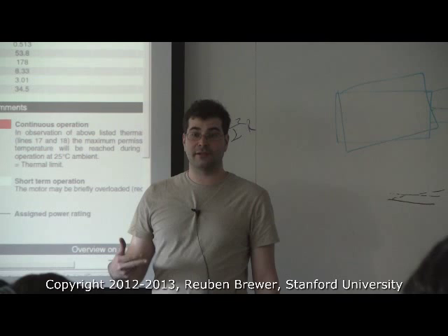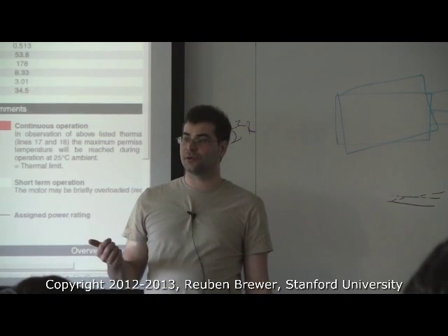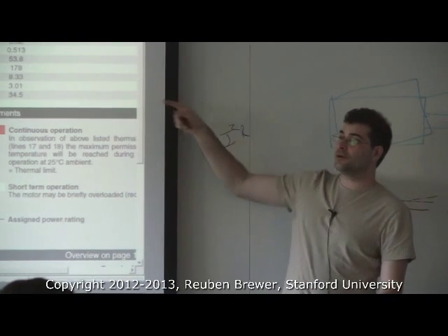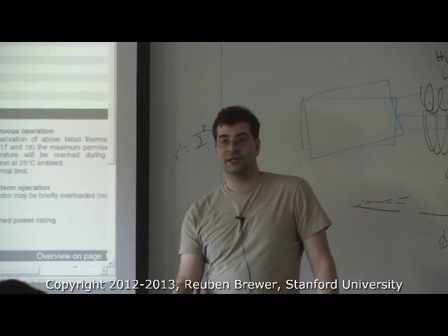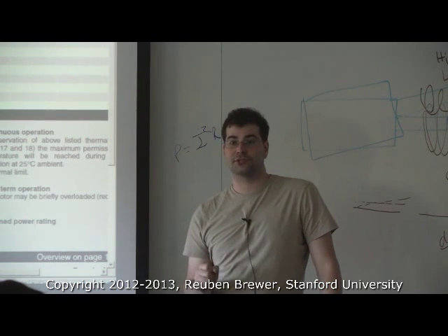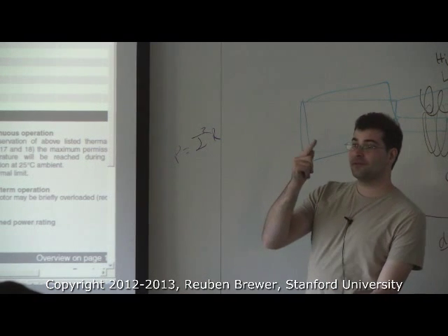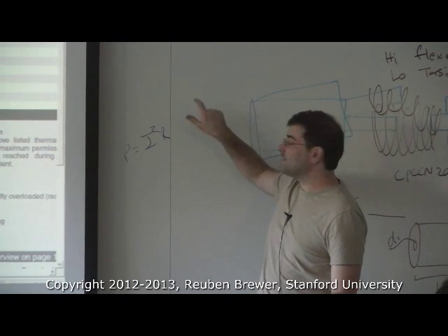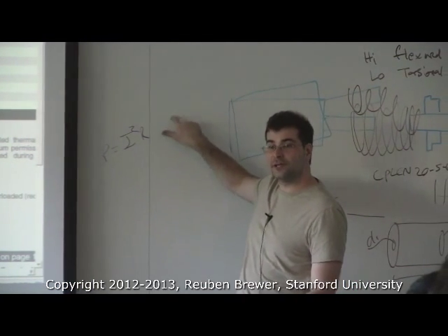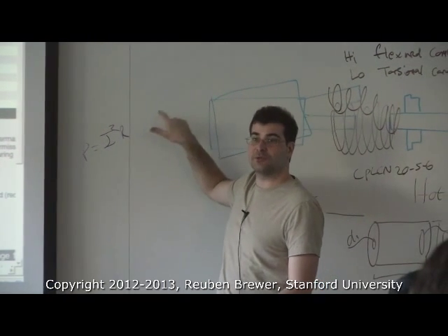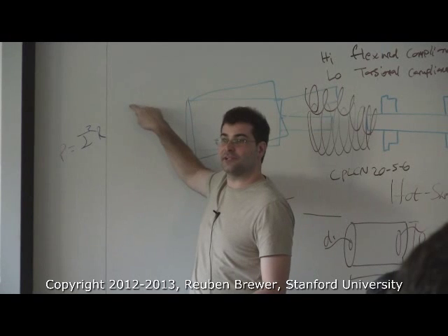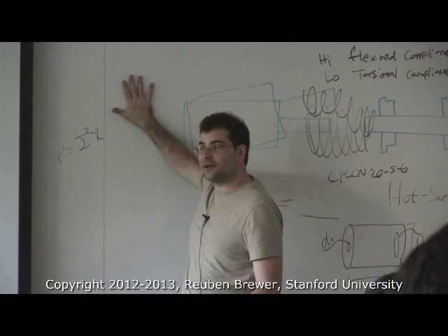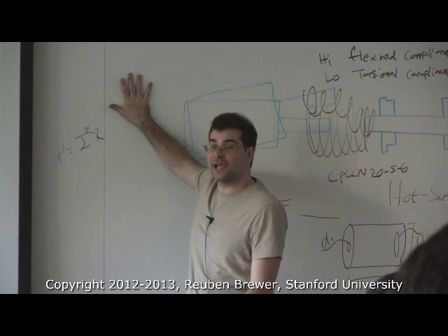And if you want to start using it regularly, like if you're doing haptic devices, let me tell you what happens if you rely on peak current for a haptic device. Say you do make a thermal model, so it doesn't torch. My proxy is about to hit this wall, and I want it to feel crisp. So high force, great. If I'm tapping, this is perfect. This is low duty cycle. My motor gives me a little extra punch and has time to cool down. Now as the frequency increases, I have less and less time to cool down. At some point, if I have continuous contact and I want to keep that same force, what's going to happen?